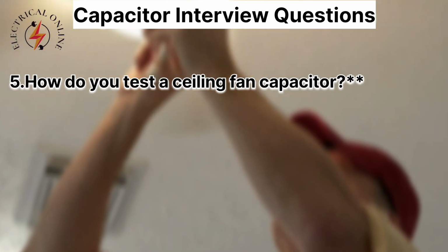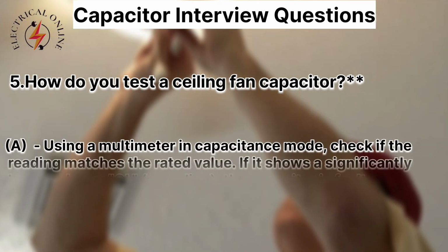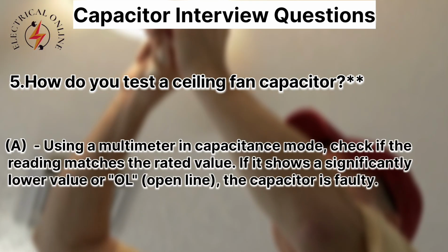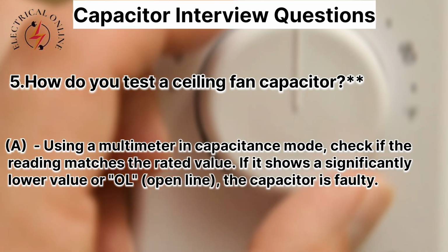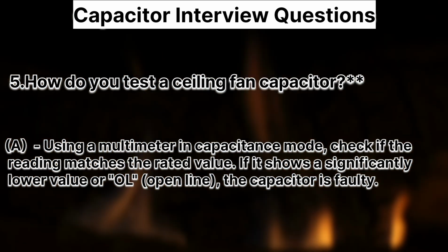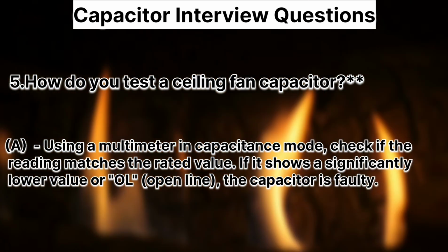5. How do you test a ceiling fan capacitor? Using a multimeter in capacitance mode, check if the reading matches the rated value. If it shows a significantly lower value or OL, open line, the capacitor is faulty.